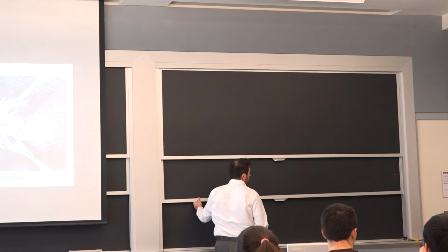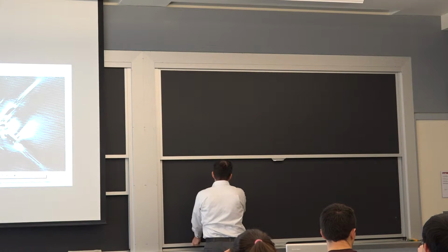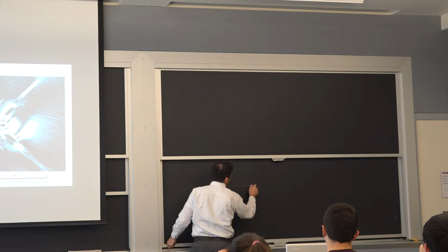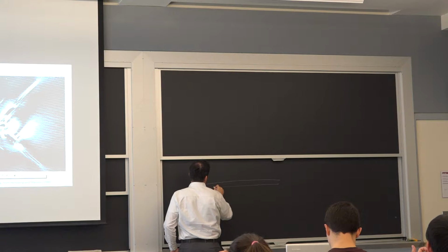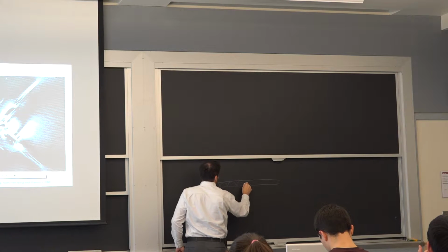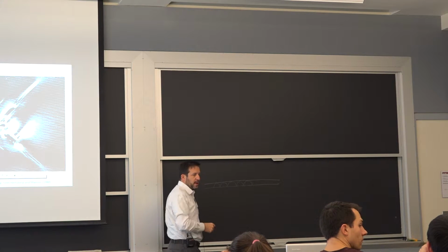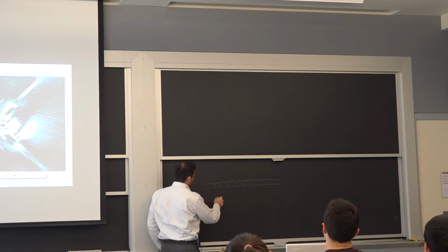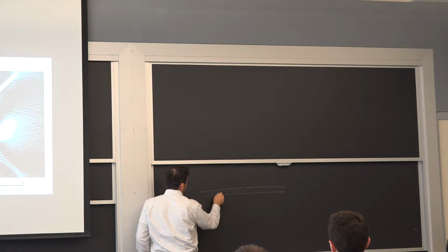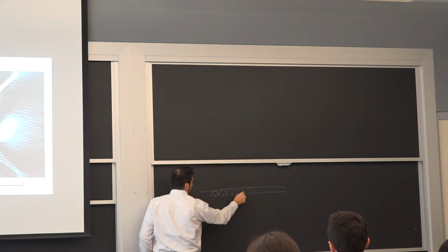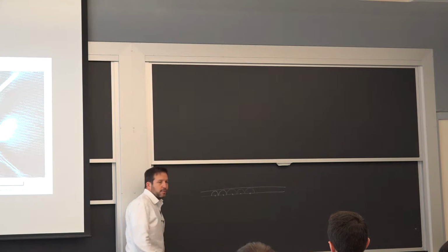You can look at those, of course, with a microscope, but just with the naked eye, on the side wall that has the pre-crack, you see a lot of little shapes like this, kind of half circles. These are indicating a point in time where the crack was almost through the thickness, so almost leaking. It's also what we call a crack arrest line. It means that if at some point I was here and I was there, I started a crack somewhere here in the middle. So the X are locations of crack initiation.